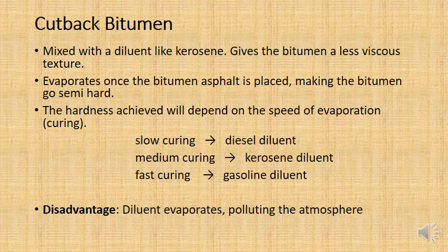So it can't wear out. Now, as it's evaporating, what we call this evaporation of the diluent, we call that curing, not to be confused with the curing of concrete. But they do achieve the same thing, because basically the asphalt is going hard as the curing takes place, and getting stronger, just as the curing with concrete actually makes the concrete stronger.